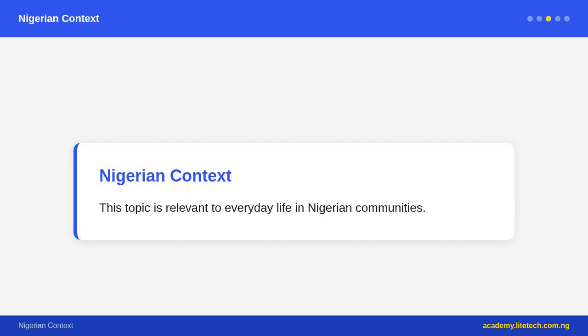Stretcher bond is the most common bonding pattern used in Nigerian block construction. In stretcher bond, all the blocks are laid with their long side, the stretcher face, showing on the wall surface. Each block overlaps the joints below by half a block length. Stretcher bond is used for single-leaf walls, walls that are 1 block thick.